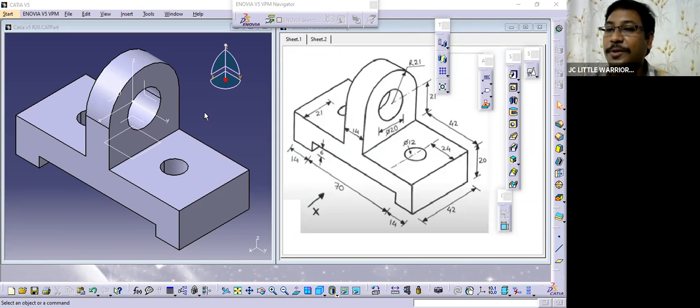We are using options like adding thickness from both sides. For example, we created this pad rib also, and again we added thickness from both sides. The reason being, we consider this origin at the center. If you consider it here, you can simply model it with a single profile.